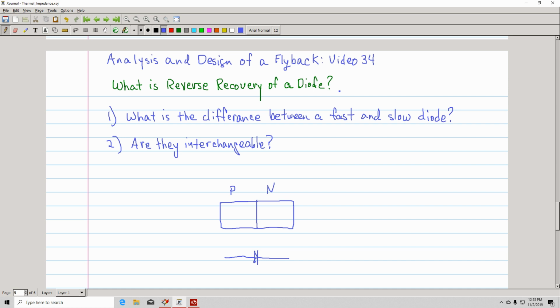They would fail short, and at that time we would replace them with regular 60 hertz diodes and put them in the switching power supply, and the power supply would heat up and short the diode again. At the time I was a fairly young man. I didn't know the difference between a fast diode and a slow diode, and putting a slow diode in place of a fast diode didn't work.